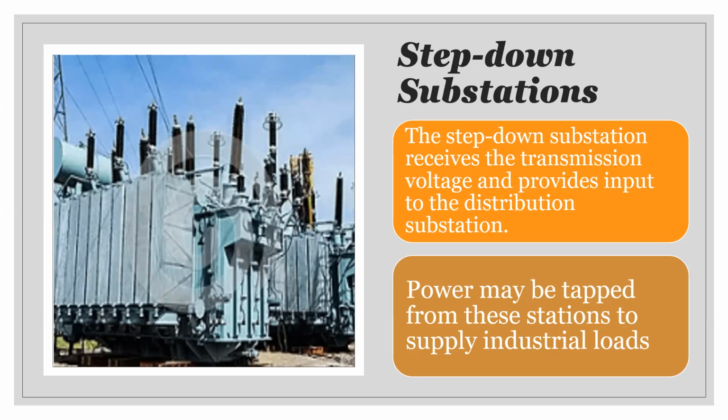In the strict sense of what we're talking about here, it would not be, because what we're saying, we're providing input to the distribution. So it's taking it from the high transmission to a lower, or if you want to call it a sub-transmission voltage. Because our voltages are so low, in terms of the input to our distribution substations, their input is primarily 69 kV. So we take in 69 kV and bring it down to 24, and the 24 is what is now on the streets. But the 138 is what we transmit across country.